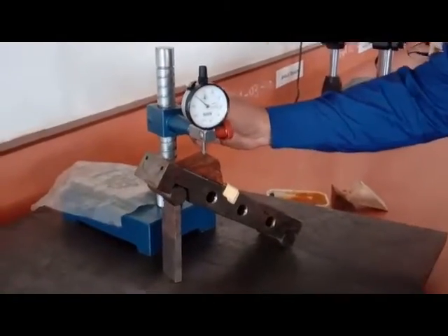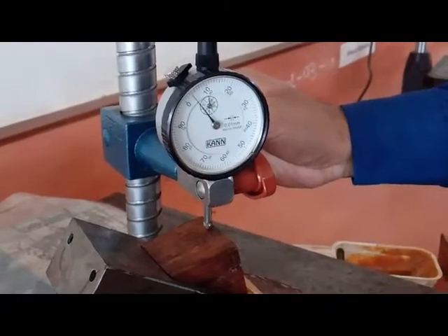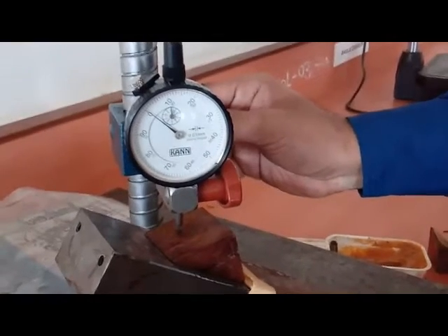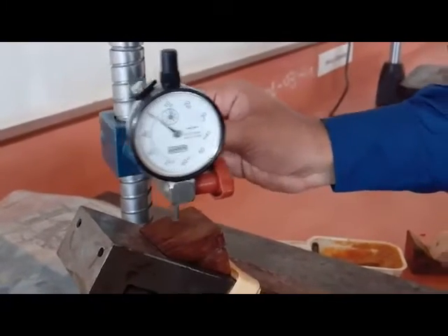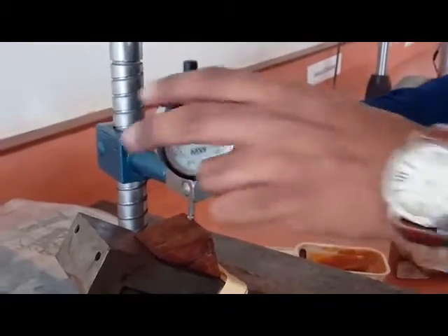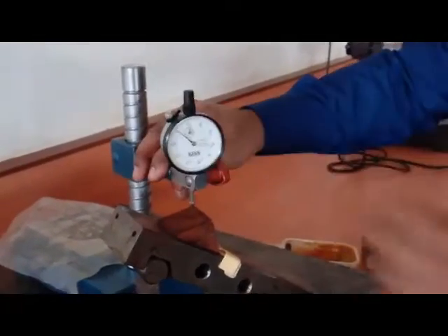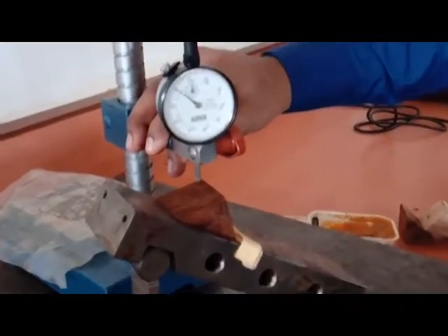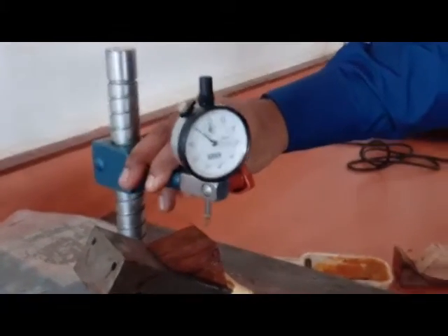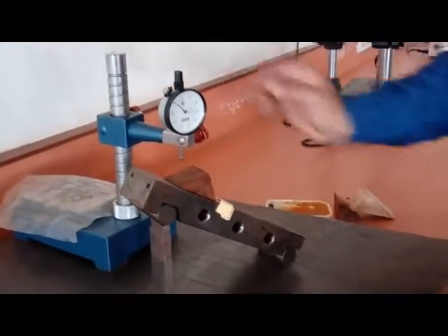As you can see, the very first point is showing deflection. After touching, we will similarly check at different points. It will show deflection if it is there. Again at different points it shows a deflection. Likewise we will be checking deflection at different points. Therefore the deflection will be counted, and if it is in the permissible region we can say that the component is parallel with the surface plate. So we will remove the dial indicator.